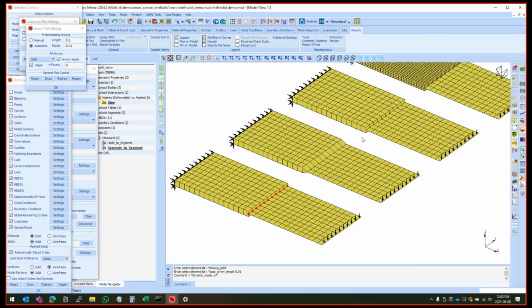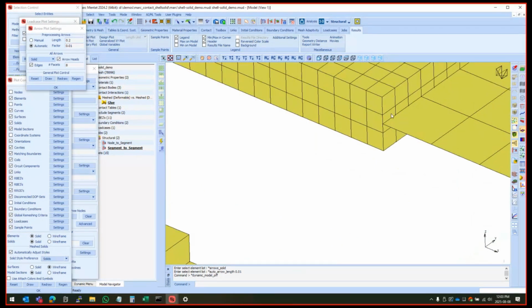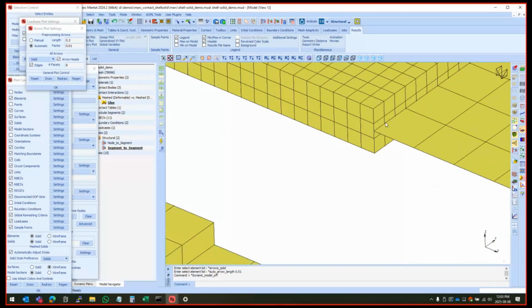Now, I'll get to this one in a moment. The complexity comes in with that method. What do we do when we do not have a one-to-one relationship between nodes? Should that node be connected to only those two or to all of them? The right answer is, well, actually to all of them, but then it causes interesting additional issues. But the biggest issue is what happens to these nodes on the solid there, which do not connect to anything on the shell.